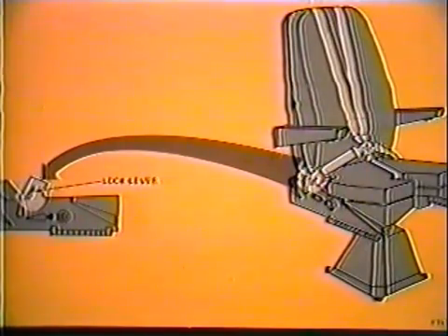All 3 crew member seats have the same restraint system. This consists of a dual shoulder harness with inertia reels, a lap belt with retractors that has lock levers to lock its position, and a crotch strap with retractor is also provided.